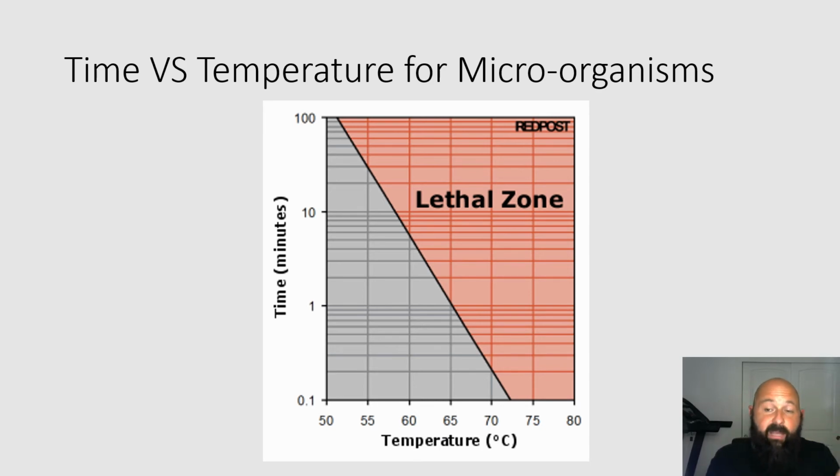Now, for sanitizing tanks with steam, realize it's really hard to heat a stainless tank evenly. Very hard to heat a stainless tank evenly. So in larger winery scenarios, you've got to go through a long process of heating a tank, because you can end up flexing and bending a stainless tank, and you can break jackets and things like that. So it's not as easy as it sounds. It can be a little bit challenging. This is particularly important for people that are doing kosher wine production, especially in larger winery scenarios. Being able to heat that tank evenly so that you don't crack it is pretty important.